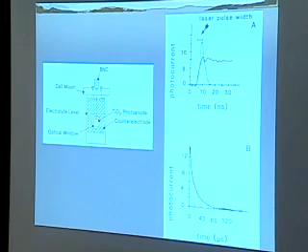There's lots of opportunities at a semiconductor electrolyte interface to generate noise. And so we made everything coaxial. That is, we have a coaxial wire going in through a BNC connector, and we have a counter electrode here, which is a platinum gauze in a cylinder. And we just cut a little hole in that gauze, and we put our TiO2 electrode right down the center. So the whole electrochemical cell is a coax cell, and that really cuts down on the noise. We carry the coax all the way into the cell. And when we did that, we could get a pretty reasonable signal.